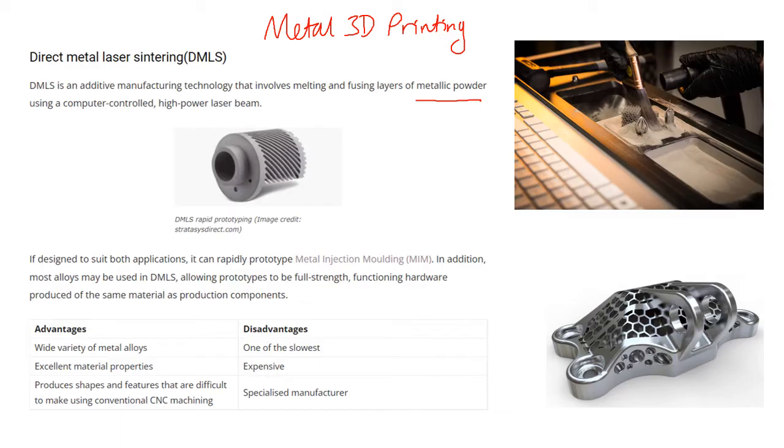And basically what is done is, if you imagine this is kind of like the base of the 3D printer, there is a layer of powder, this metallic powder, and you can see that on this image here being brushed away. And every time the model is sliced into its different layers, each layer will have different shapes that it needs to print on top of each other, it uses a laser beam, if I use a different colour here, just to fuse and melt certain parts into the powder.